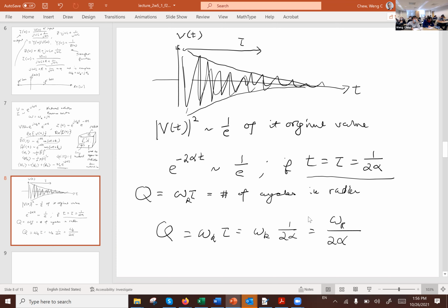Where we take the complex resonance to have a real part plus an imaginary part. Okay, you will have the real part and the imaginary part, and if we take the real part, divide by the imaginary part and divide by 2, that would be the Q of the system. That is the simplest definition of Q that I can think of. So are there any questions regarding the definition of Q? Yes, Geoffrey.